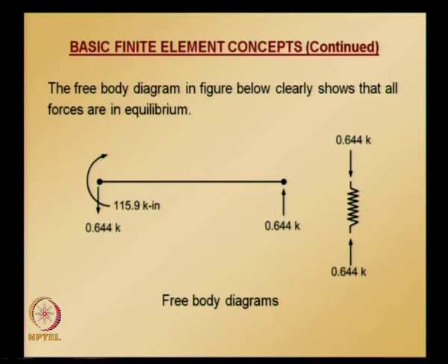For analysis of structural frames we will be using whatever we learned till now, that is the beam element equations and also the equations that we developed for axial deformations. So the beam element and axial deformation element presented in the earlier lectures are combined together to form a general element for analysis of 2 and 3 dimensional frames.